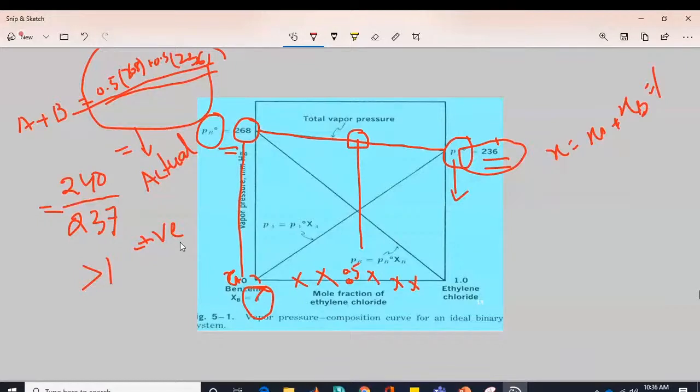When definitely there is a pressure difference from high pressure to low pressure, then definitely that fluid or liquid is going to vaporize. Flash distillation is known as equilibrium distillation, such that separation is attempted when the liquid and vapor phases are in equilibrium. Remember, vapor and liquid to be in equilibrium. This method is frequently carried out as a continuous process and does not involve rectification. So this is a process where we do not rectify or purify the components.